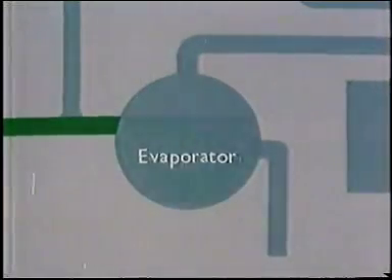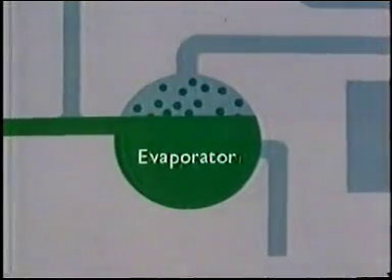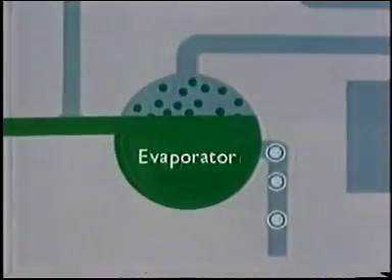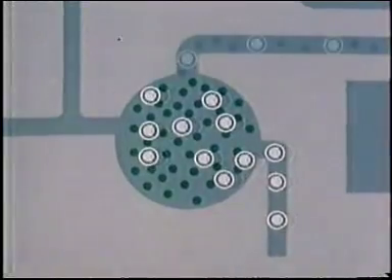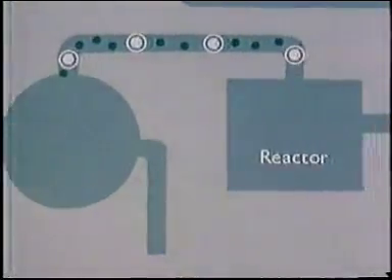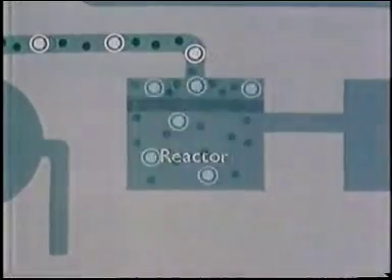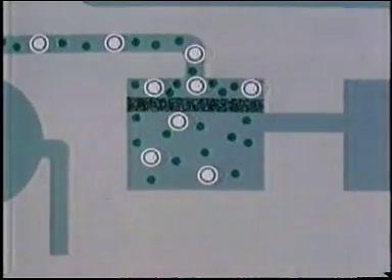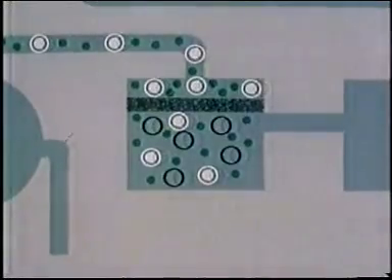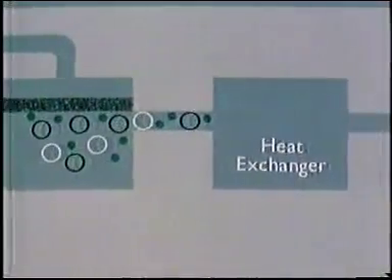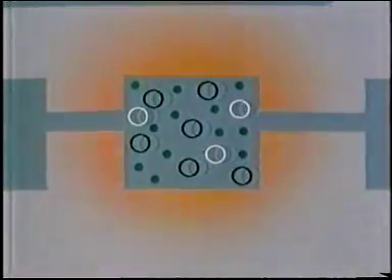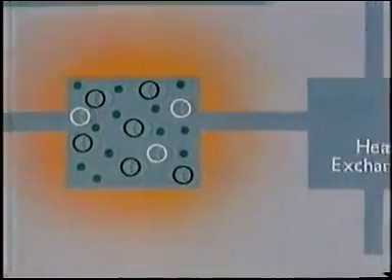The ethanol starts in the evaporator, where it is vaporized, and then mixed with air, which contains oxygen, our other reactant. The mixed gases are led to the reactor. Here they pass through a layer of catalyst, and it's here that the chemical reaction occurs to produce acetaldehyde. All of the oxygen is used up, but not all of the ethanol, because it is deliberately in excess. The products go next to the heat exchangers, where their heat generates steam for use in a later purification process.